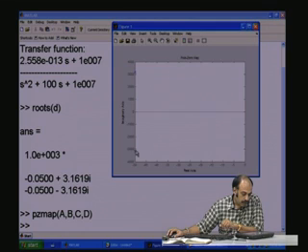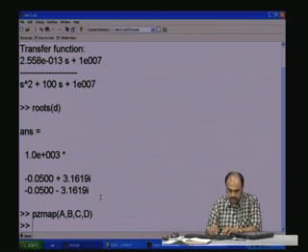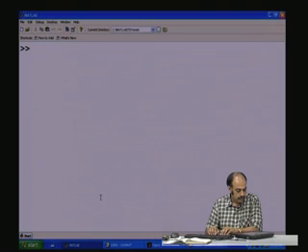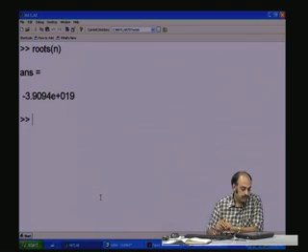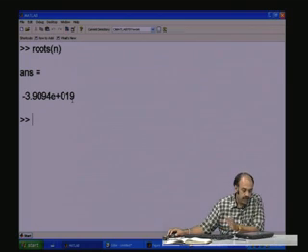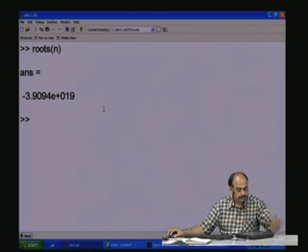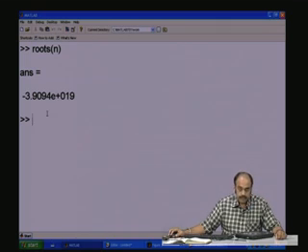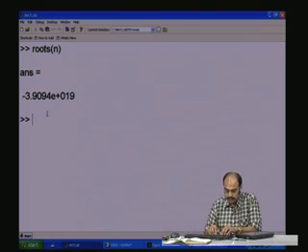Now, there is also a 0 location, which is basically the roots of the numerator. So, roots of the numerator will give you the 0, and the 0 is located at this portion. It is quite far away on the negative real axis. This can also be obtained from the state equation, that is the A matrix.